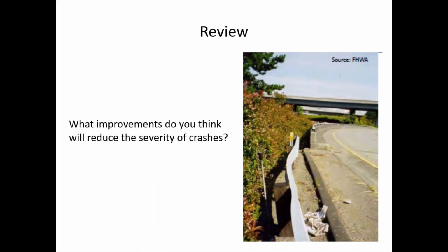All right, thanks, Ron. The first few comments: getting the curb flush or behind the guardrail, move guardrail out in front of curb, proper bridge terminal assembly, move guardrail even with curb, delineators, no curb in front of rail, need proper transition from rigid to semi-rigid barrier.